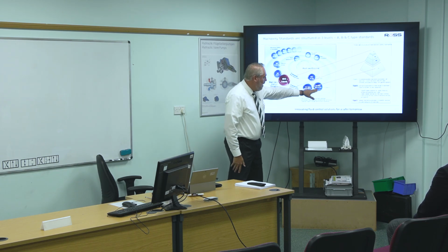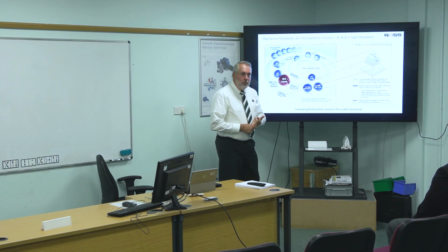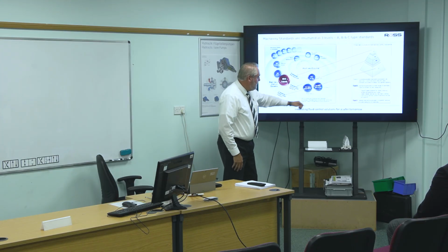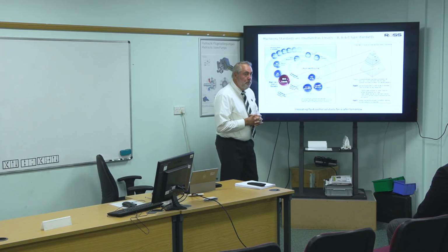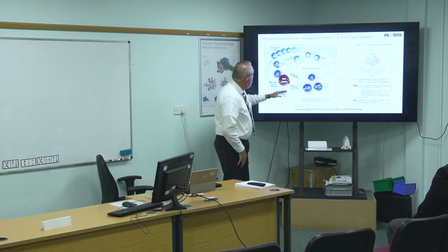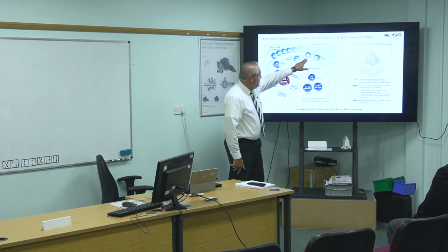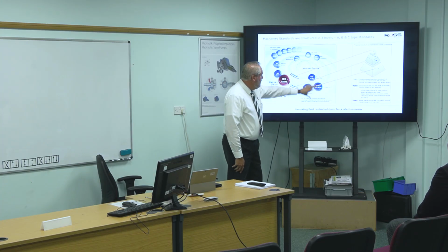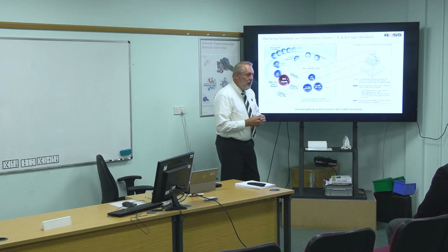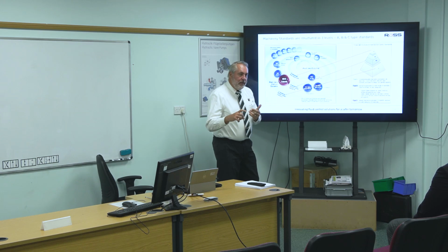Like there's a standard for hydraulics called ISO 4413, one for pneumatics, ISO 4414, ISO 13849, which is for machine safety design. You get into IEC 61800, which deals with things like drive systems. IEC 61508 deals with electrical and electronic circuit boards. So these B standards are more what I call product or application standards.